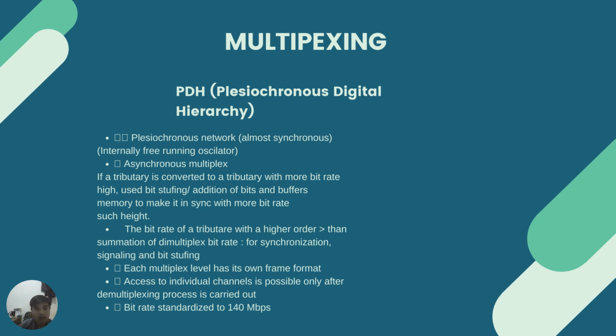And each multiplex level has its own frame format, and access to an individual channel is possible only after the demultiplexing process is carried out. And the bit rate is standardized up to 140 Mbps. So it's big, right?